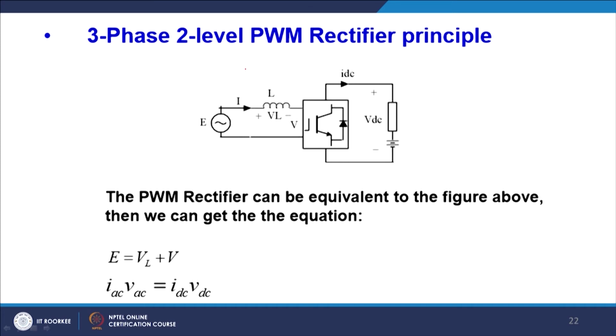So, this is the single line diagram. Generally, this is for the battery charging application. We want to charge our battery at unity power factor. Then this will be an inductor, and this is the IGBT, and that can be operated as high as 20 kilohertz for the lower power rating. I will show a little data on it.